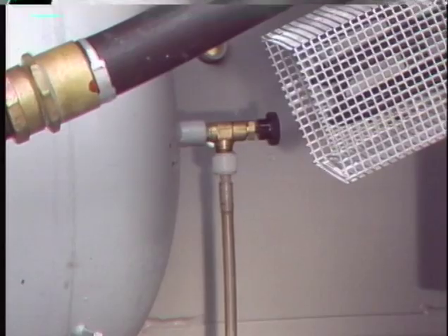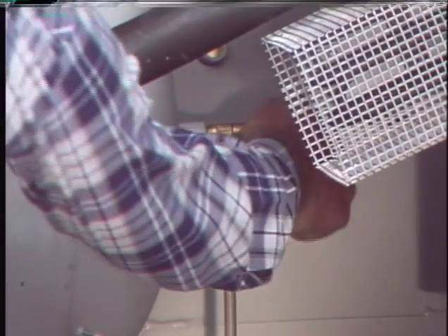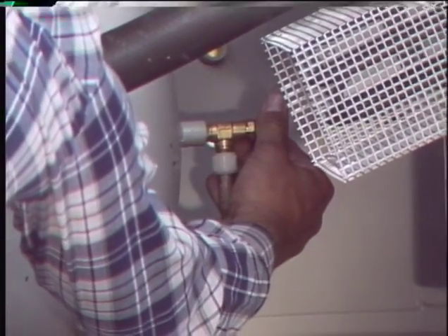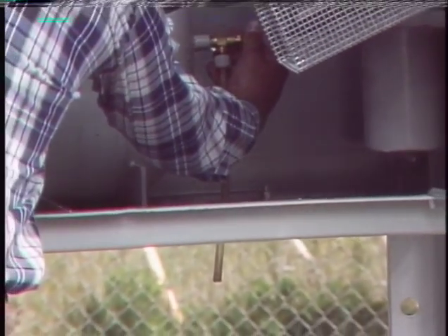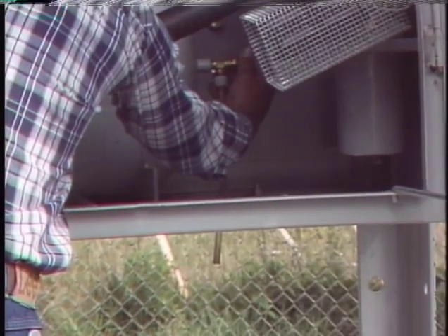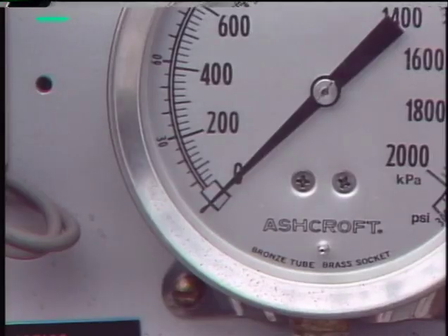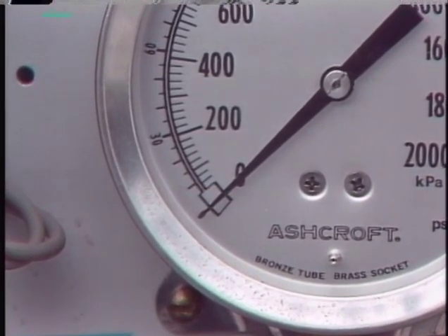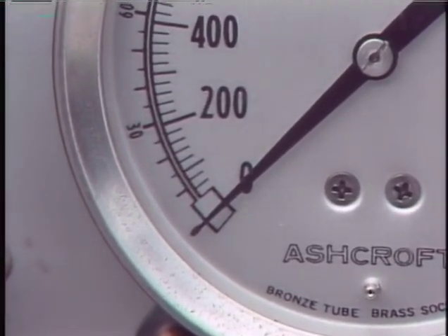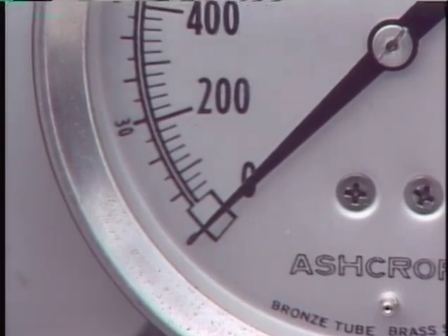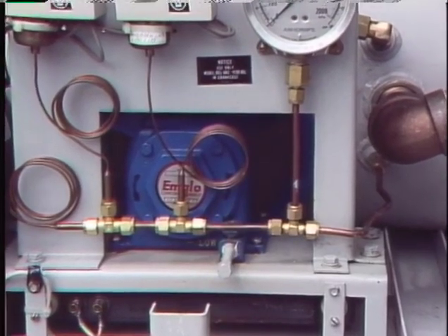Here, the compressor circuit knife switch is open, so the circuit is de-energized. Then a bleed valve is opened to discharge the compressed air and bleed system pressure to zero. When the valve is open, it's normal for some water to blow out with the air. Water can accumulate in the reservoir due to condensation. After air pressure is bled to zero, the valve is closed and the operating mechanism can be cleaned, inspected, and checked for adjustments. The compressor is also serviced.